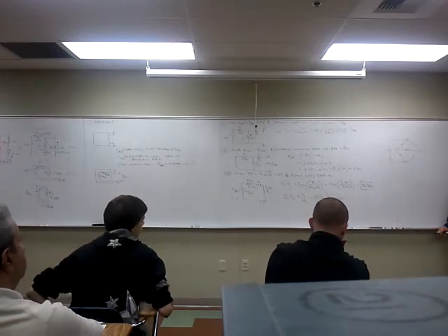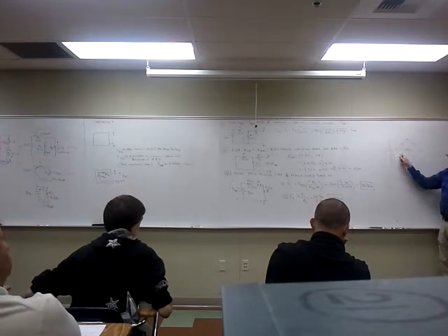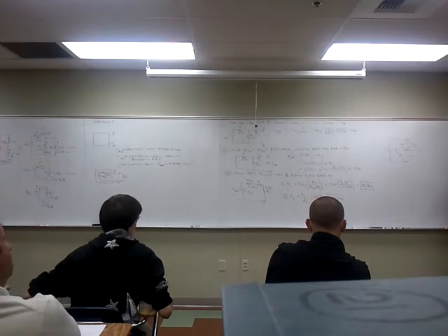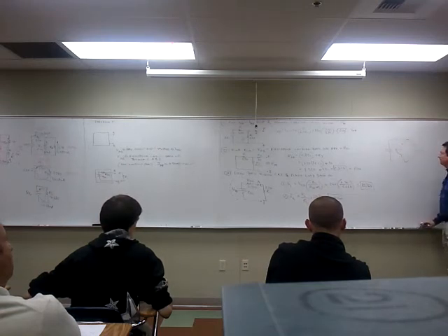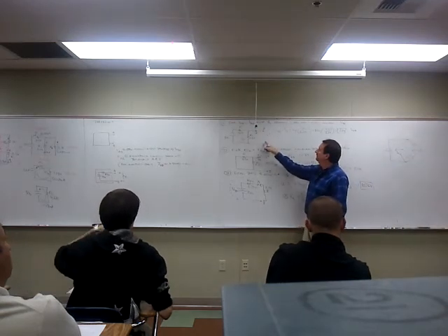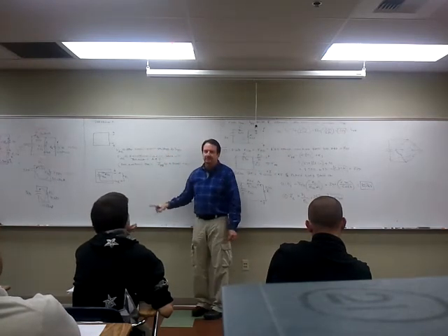So what other theorem did you learn that you could solve this? There's one that you've learned already that would do this. Mesh, yeah. You make a loop here, you make a loop here, you make a loop here. You have 3 equations with 3 unknowns. It becomes a mathematical exercise, doesn't it? But with Thevenin's, since typically what you're concerned with is the center resistor, what do you do? You remove it. You call that the load. And what's the first thing you do? You remove the load. Because what is the definition of Thevenin? It's the open circuit output voltage between terminals A and B.